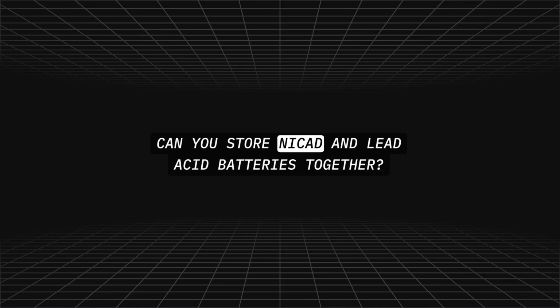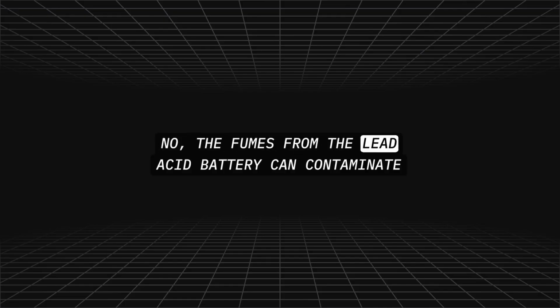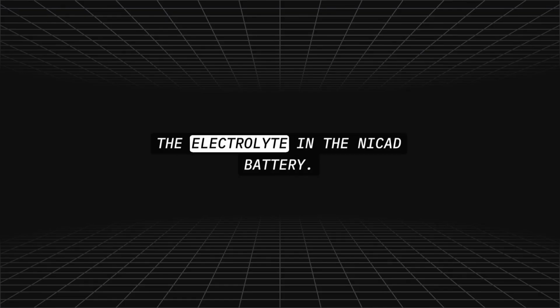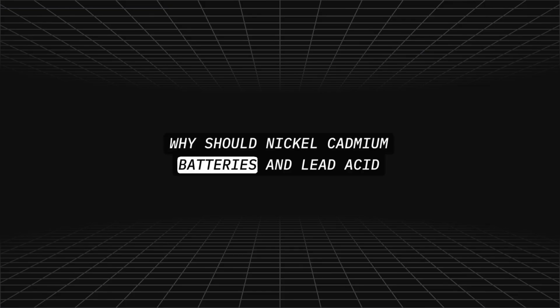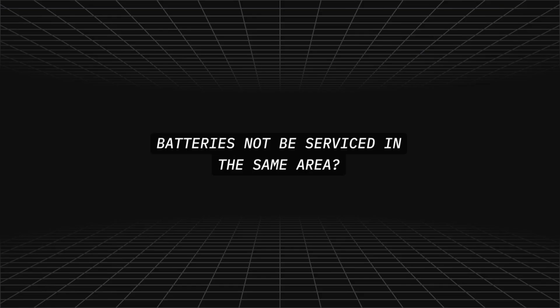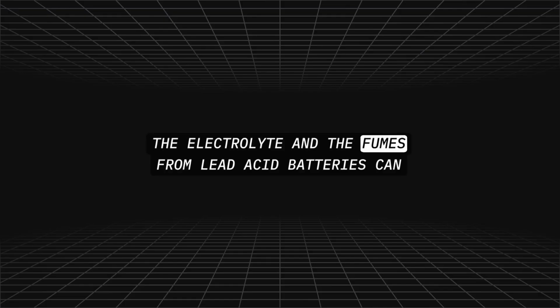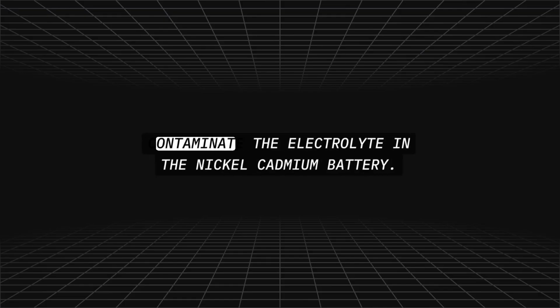Can you store NiCad and lead-acid batteries together? No. The fumes from the lead-acid battery can contaminate the electrolyte in the NiCad battery. Why should nickel-cadmium batteries and lead-acid batteries not be serviced in the same area? The electrolyte and the fumes from lead-acid batteries can contaminate the electrolyte in the nickel-cadmium battery.